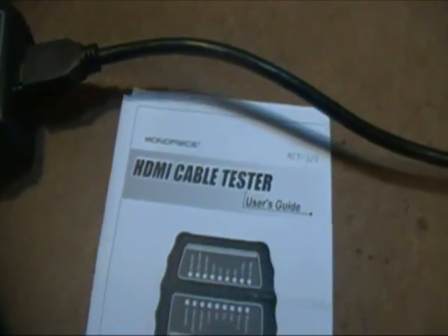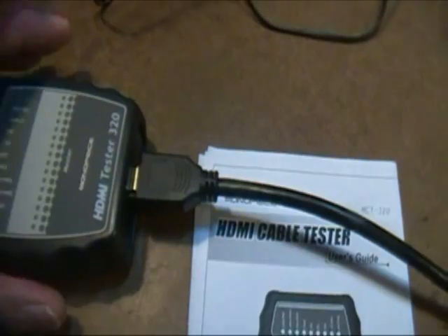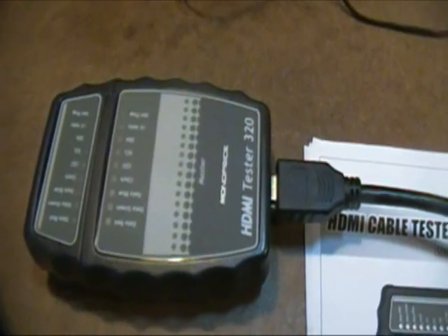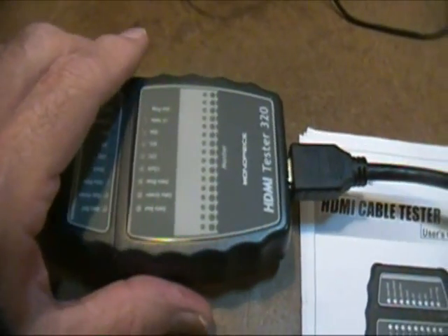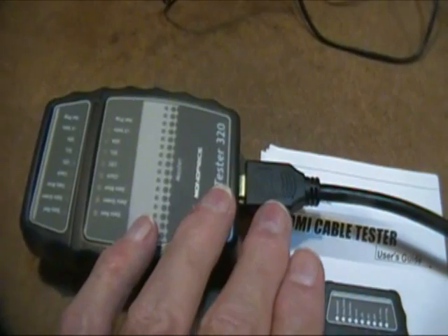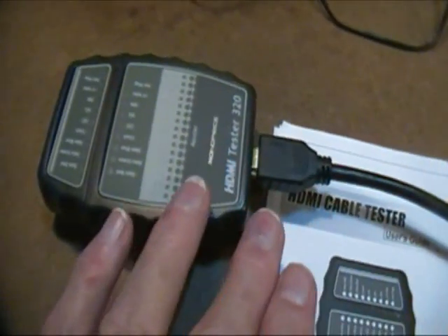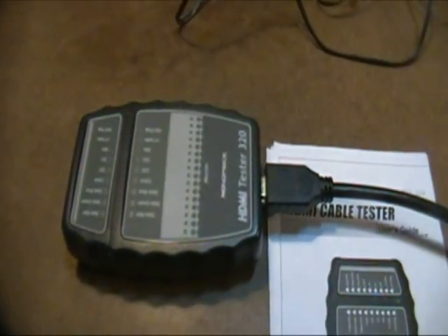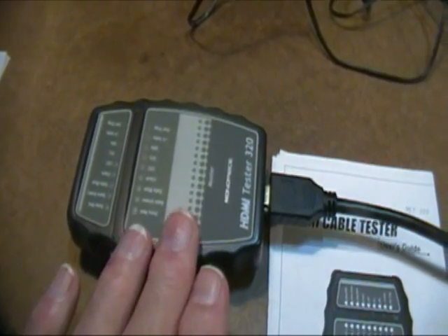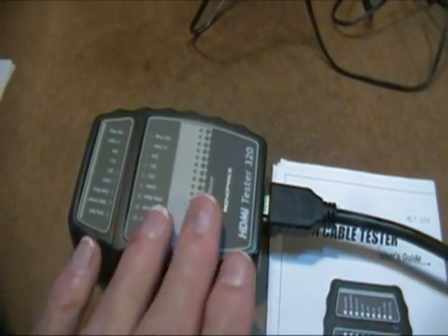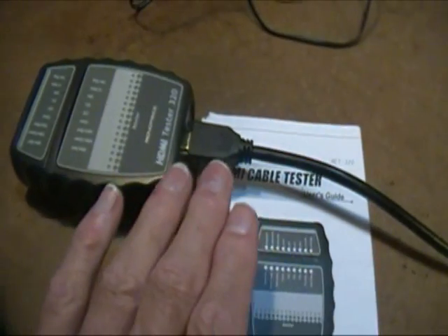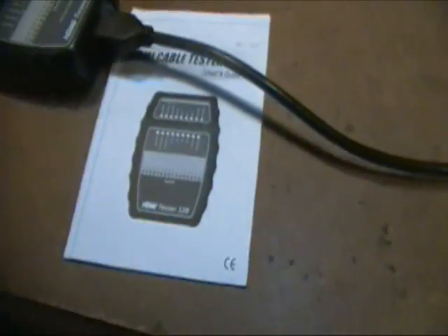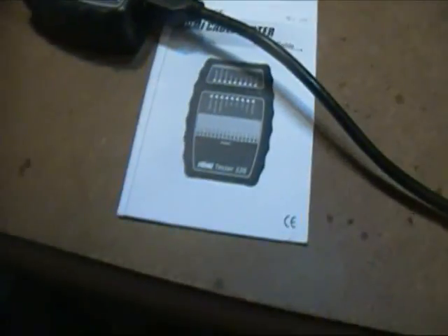Okay, let's talk about testing HDMI cables. Now, I've had no failed HDMI cables out of perhaps 100 or so that I have used or installed or tested over the last couple of years. I have never found a bad one, but there are potential problems, the connections in here as well as broken wires and other things. But understand that a cable tester like this does not actually test the cable under the high definition protocol. In other words, it basically just tests whether the wires connect from the proper pins here to the proper pins over here.